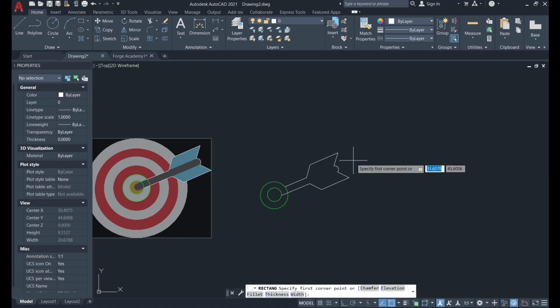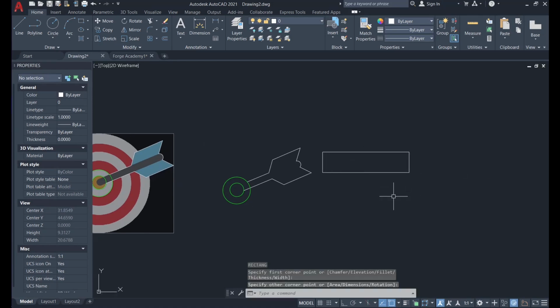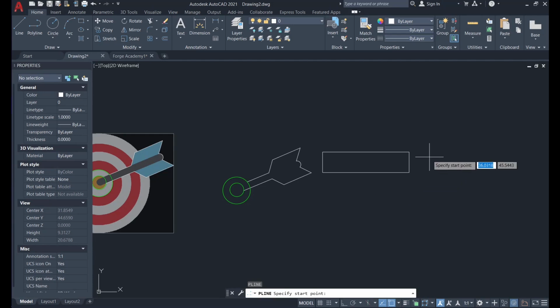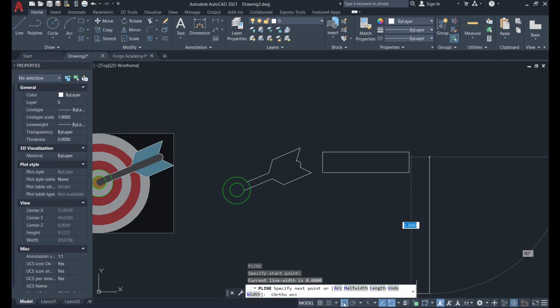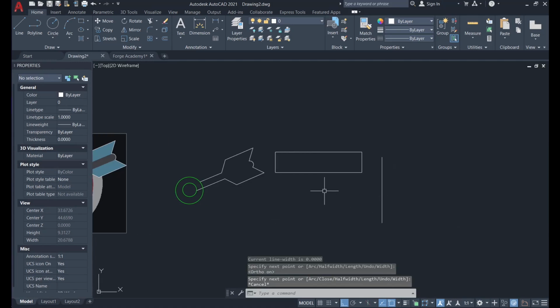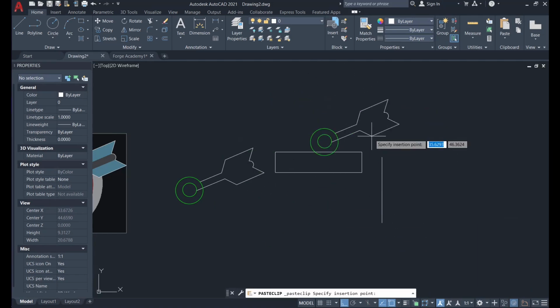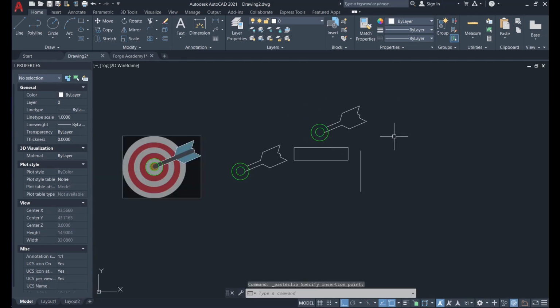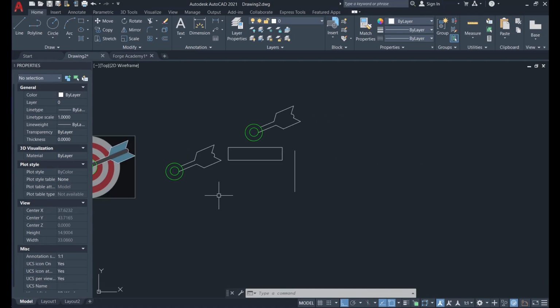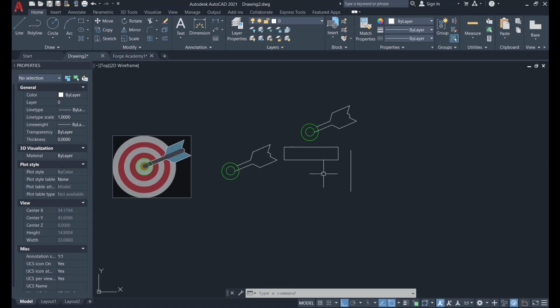Let's say that I'm going to do a rectangle and another polyline with ortho mode. Okay. And now when I'm using the paste shortcut, Ctrl V, I still have from clipboard my drawing, my shape that I have copied with a base point. So that's why this is very helpful, because you can keep drawing if you forgot something and you will still have your last copied shape or image or whatever in your clipboard,